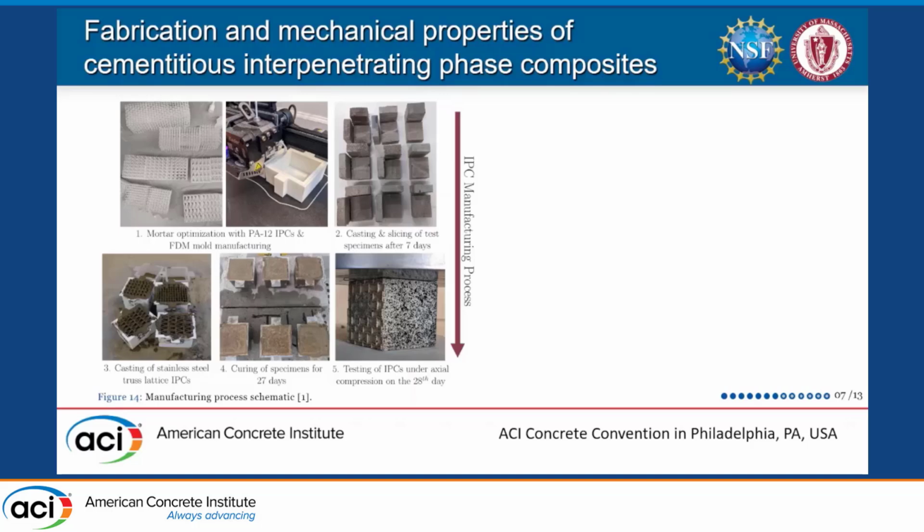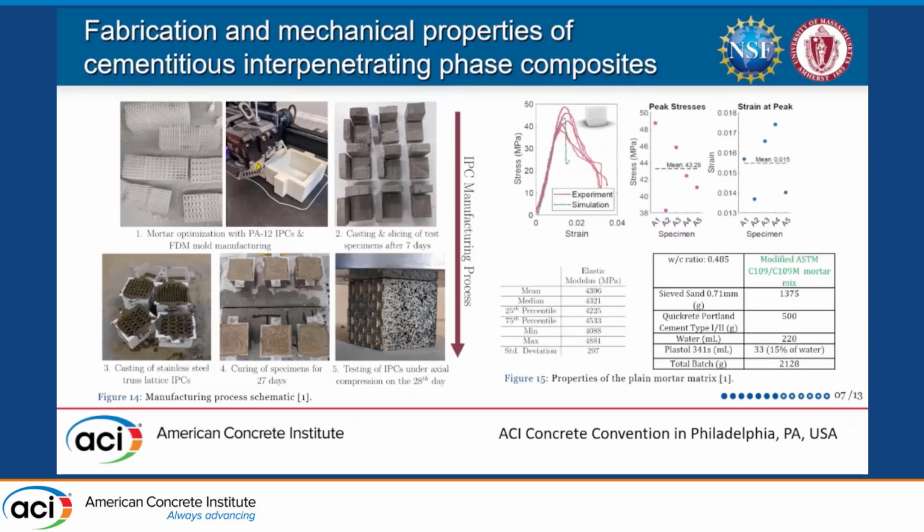And we were also interested in seeing if there are any voids in the composites, which we were eventually able to remove from these composites. After we did this preliminary work, we were able to cast the stainless steel truss lattice specimens, cure them for 28 days, and test them under axial compression on the 28th day.